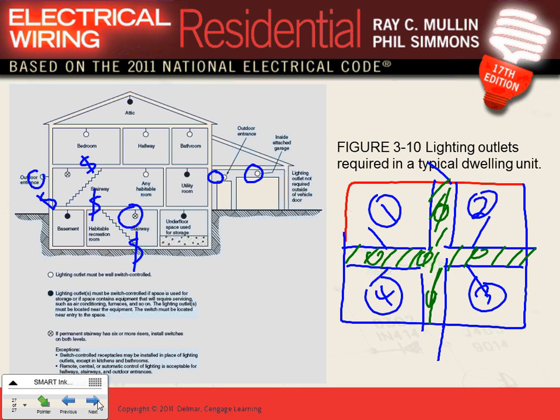The last thing I forgot to mention. I keep saying the last thing. Arc fault circuit interrupter. Arc fault circuit interrupter. Please add this one. Now, arc fault circuit interrupter, required since we in Minnesota adopted 2011. I want you guys to remember, arc fault circuit interrupter applies to the following: receptacles and lights. Can you guys write yourself receptacles and lights?